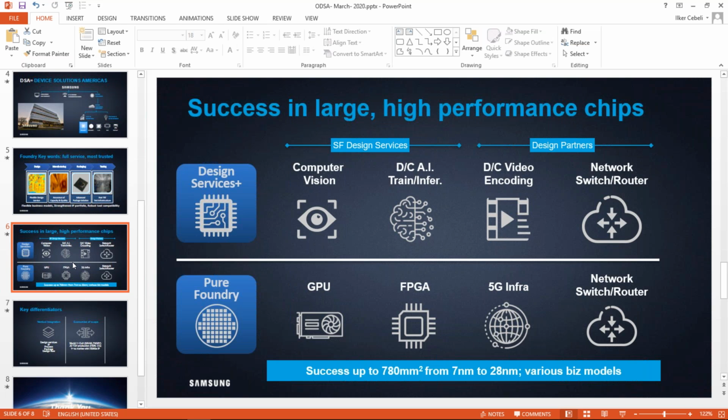Hey guys, this is Elko from ASE. If I could chime in for a minute on that. You're right that all the HBM SoC integrations in production today are probably heavily leveraging silicon interposers. The reason is, as Ilker indicated, you've got this micro bump interface, 45 to 55 micron micro bump pitches, so you need the high density routing that an interposer provides, with less than half micron line and space.